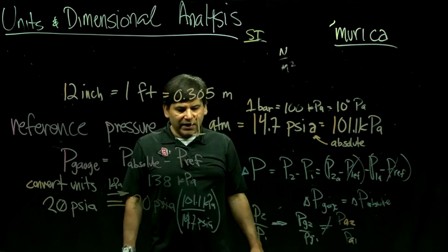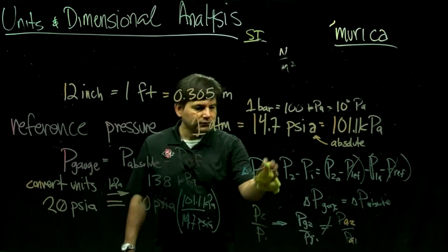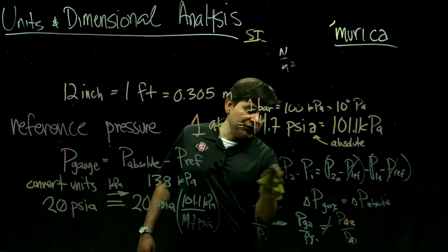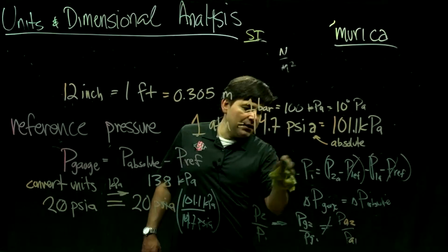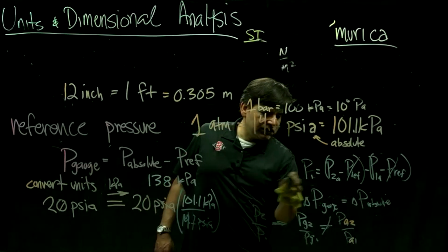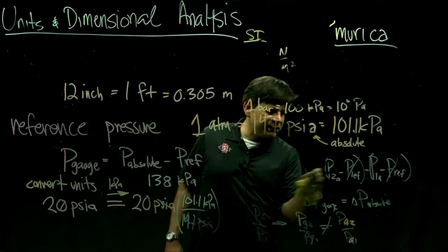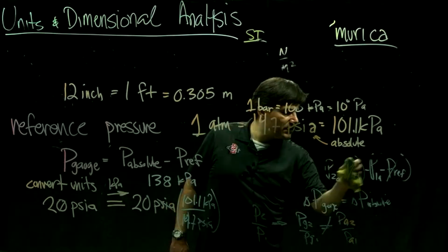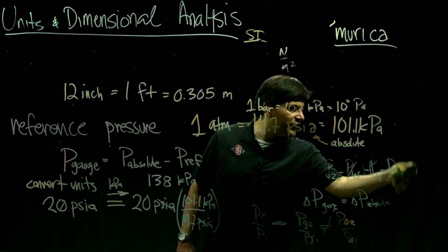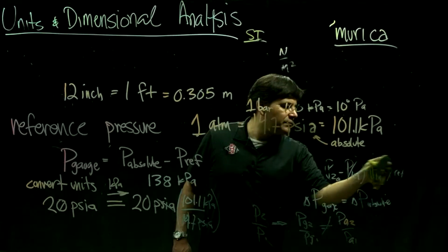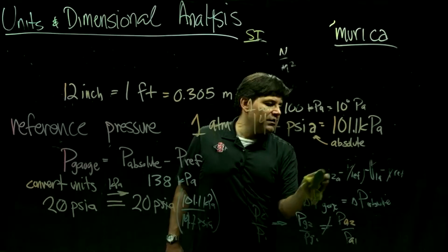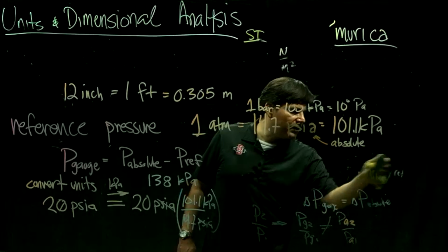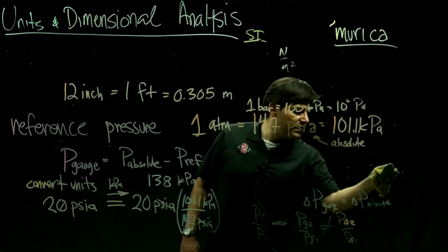So continuing with gauge pressure, let's put this here. Gauge pressure is useful in some engineering applications or some systems. Gauge pressure is all that is needed, and it's very easy to read that off of a dial, off of a pressure gauge. Pretty much all pressure gauges give an output depending on gauge pressure of what their surroundings are.